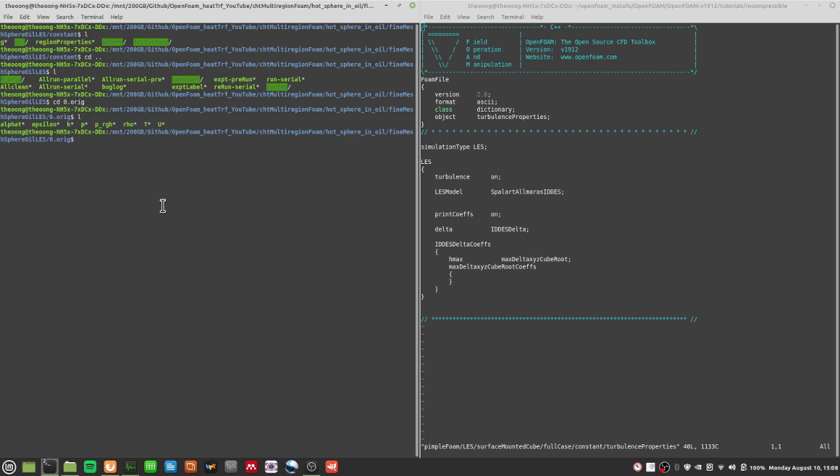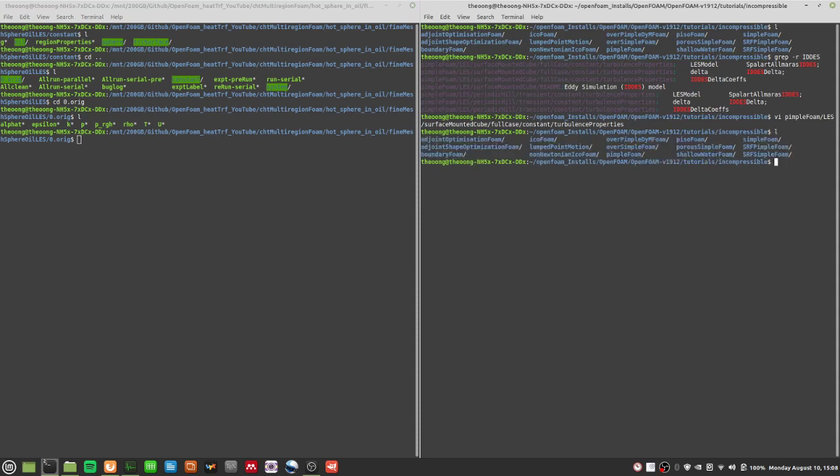I think divide or multiply, I can't remember which is which. But they'll multiply it by some factor of this turbulent Prandtl number. If you want more details, again, go and look at my turbulence modeling series. I explain it in depth there. In this video, I'm just showing you how to do the syntax right.